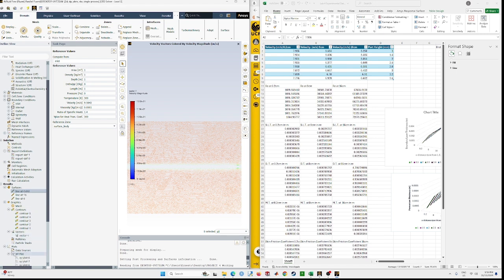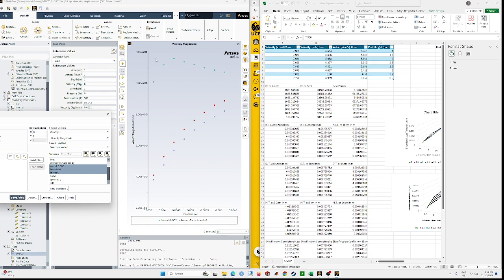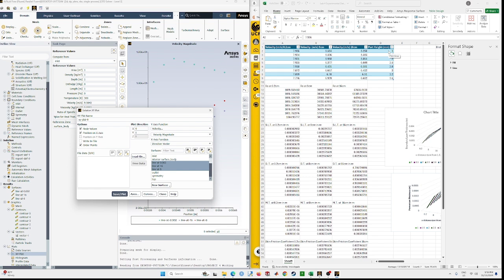Once you get those, you just go to XY plot, select them, plotting along the Y here. And we're doing velocity. There it is. The first one, they're all gonna come out a little bit funky just because that probe height at 0.2 centimeters happens to be outside of the boundary layer. We explained that in our project. But there's that part.